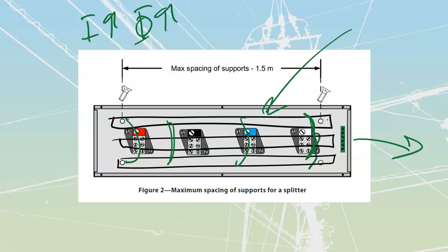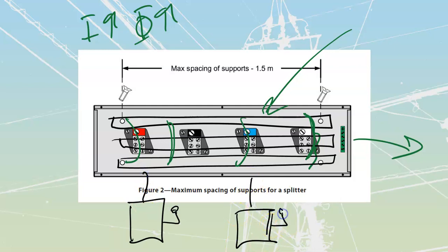Disconnecting switches that are going to be located by our splitter are all going to be covered by that 14-100 rule that we talked about before, where we've got a disconnect switch over here and another one over here. Based upon the ampacity of what we require, we're going to have these things either really close in or further out. You're going to get worksheets off of this stuff that you can work on, dealing with these taps we have inside of these.